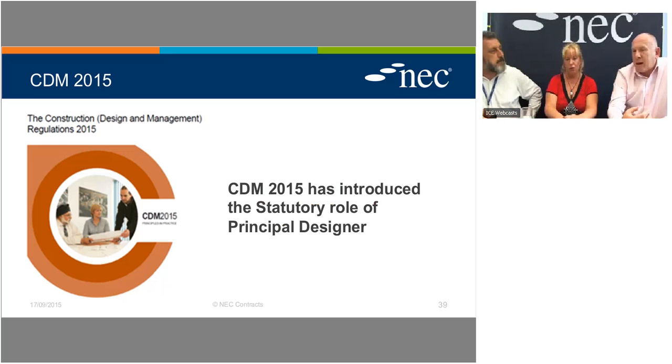I've seen in the past, other than design people, fancy their chances as acting as CDM coordinator, and I was unsure and uncertain about that, to say the least. But do you think now, with the principal designer, is there a clue there? Do you think that only a designer can act as a principal designer? It is a requirement in the regulations. The principal designer must be a designer. Okay, so that kills all the non-designers. It doesn't have to be a designer on that specific project, but they have to be a designer who understands the design. Whereas a CDM coordinator could be a project manager, could be a quantity surveyor, could be anything.